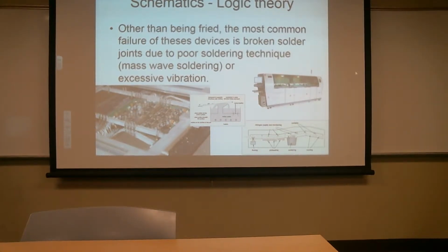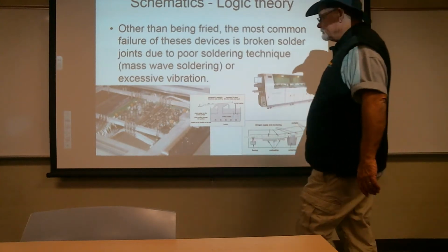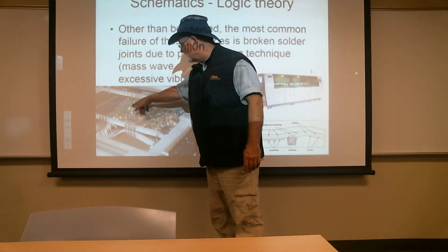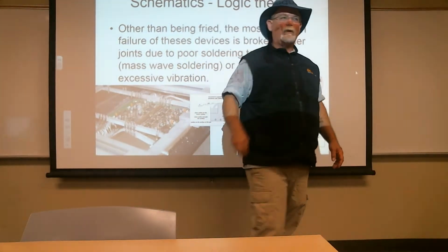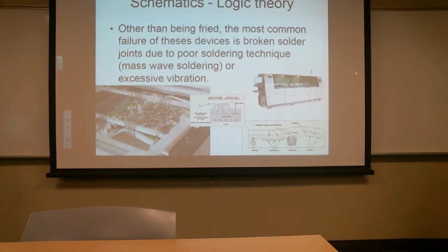That first section might actually be a preheat chamber. So depending on the nature of the board, they might preheat larger components. There's a few larger components. They might preheat them some with a blast of hot air as it's moving along. Or they'll preheat the whole board to reduce the potential for cold solder joints. And then as the board moves across the solder wave, it gets flow soldered or wave soldered, and then comes out of it, goes through a cooling process, and then ejects out the other end.